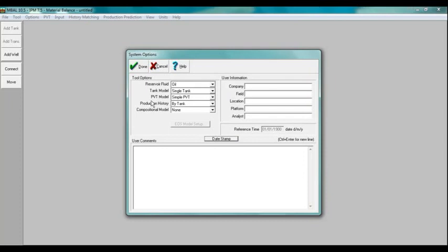Anyway, the reservoir fluid: we have four kinds of reservoir fluids. The oil reservoirs, and the gas reservoirs. Actually, the gas reservoirs option is for dry gas reservoirs. Then the retrograde condensate reservoirs, where Mbal uses the retrograde condensate black oil model. These models take into account liquid dropout in the reservoir at different pressures and temperatures. So there is a difference between the gas and the retrograde condensate.